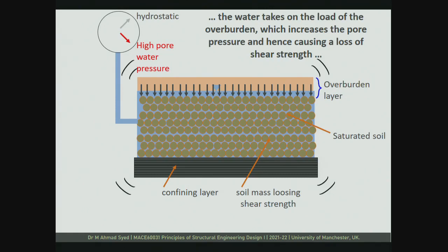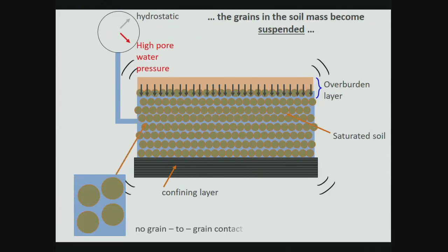Over a period of time, this pore water pressure will dissipate gradually, okay, and this configuration will transition back to a tightly packed configuration. But before doing that, there will be a state where these grains will no longer be in contact with one another, and that point defines the state of liquefaction.